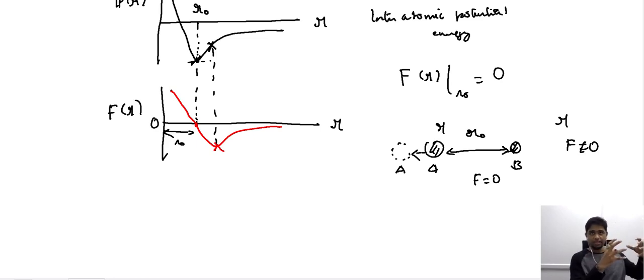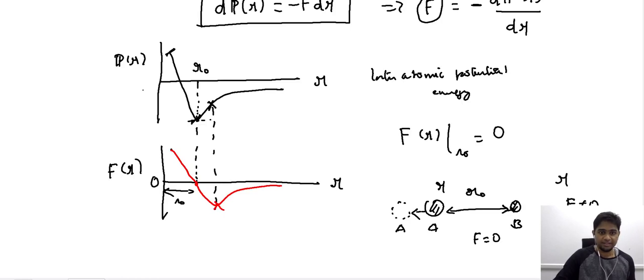So we saw the elastic behavior in terms of the interatomic potential energy. That is, the interatomic potential energy increases, and in order to reduce this energy, the atoms go back to their original state. So this is one understanding that we gained from this plot here.